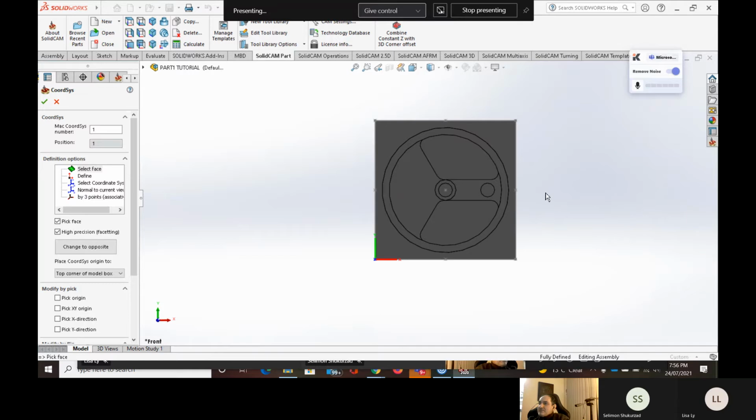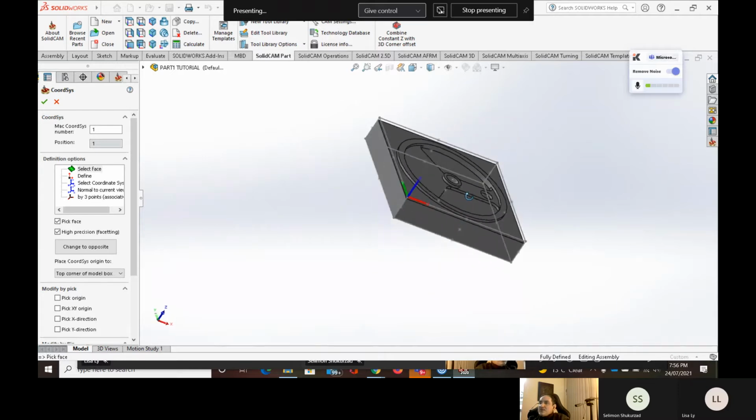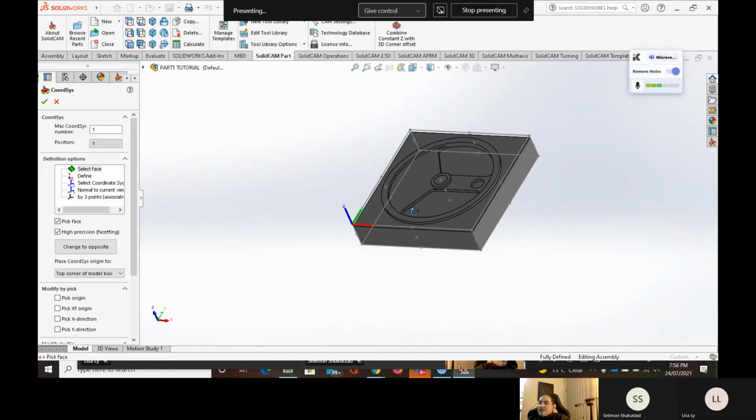this direction. If I put the center to be the datum point, and I'm going to machine another workpiece that is 120, the datum point has been defined for the machine to be here, but the new center is going to be here. So to overcome this problem, just put it near the fixed part of the jaw. So this will be the point. That was the main reason we always try to put the origin at this corner.